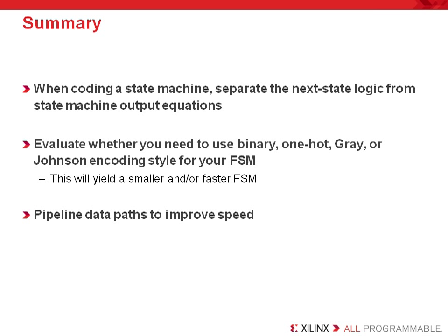Lastly, we talked about the benefits of pipelining, and we talked about the most common ways in which designers are pipelining their designs. And even in this day of the 6-input lookup table, the newest devices, this is still one of those things that designers are going to be doing. So make sure you take the time to evaluate whether your design needs to be pipelined more.